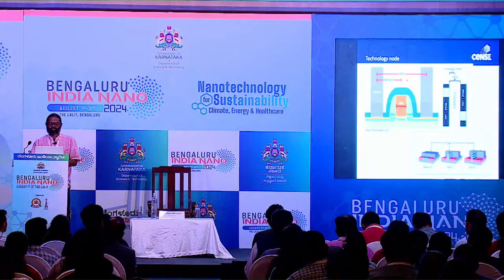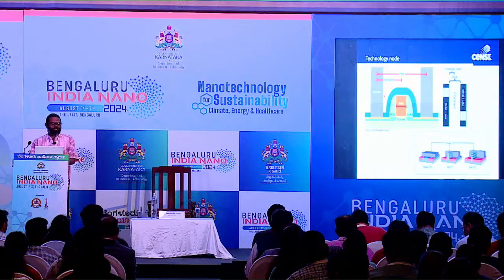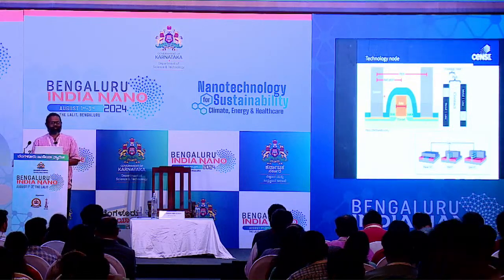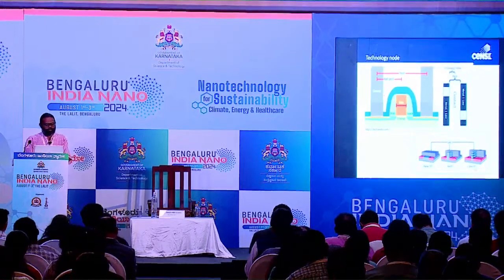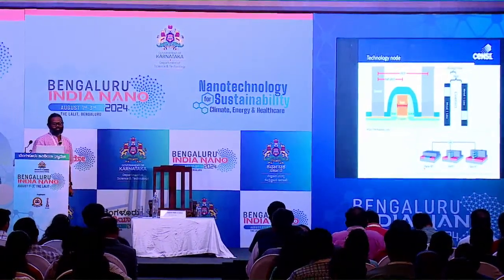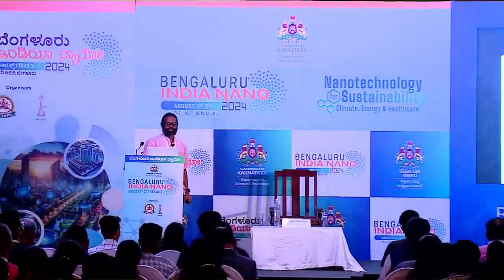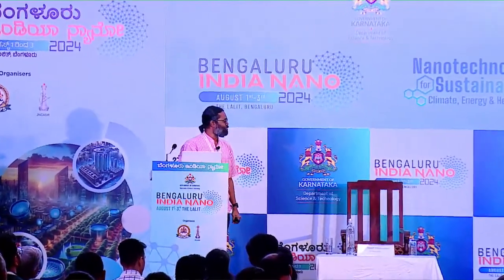And these days half pitch is also considered as a technology node. So you have to read a little bit carefully. And the reason why it becomes very difficult to define right now is because of the bottom picture that you have, right? So in the past we used to have very planar transistors, right? You have this doped region where your charge is moving and the gate is controlling, and we started to make these kind of fins, okay? It's called FinFET. And then now we have very complex multi-stack gates, which is called gate all around, right? GAA FET, field effect transistor, but gate is around, right, the transport layer.